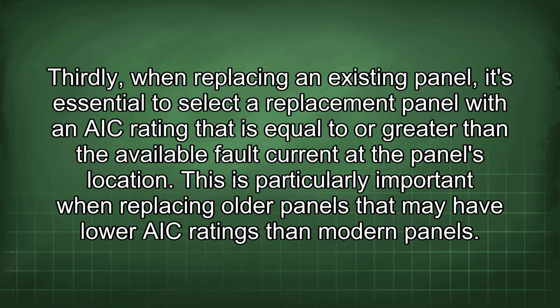Thirdly, when replacing an existing panel, it's essential to select a replacement panel with an AIC rating that is equal to or greater than the available fault current at the panel's location. This is particularly important when replacing older panels that may have lower AIC ratings than modern panels.